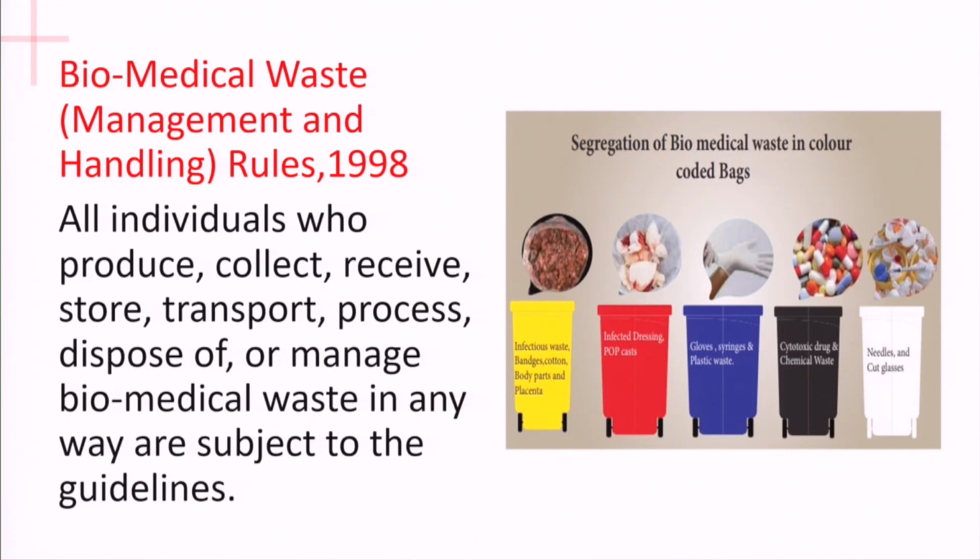Next, coming to the Biomedical Waste Management and Handling Rules of 1998. All individuals who produce, collect, receive, store, transport, process, dispose or manage biomedical waste in any way are subject to follow a set of guidelines. 10 categories of biomedical waste, which are stated in the rules schedule, are to be separated, packaged and disposed according to the regulations.